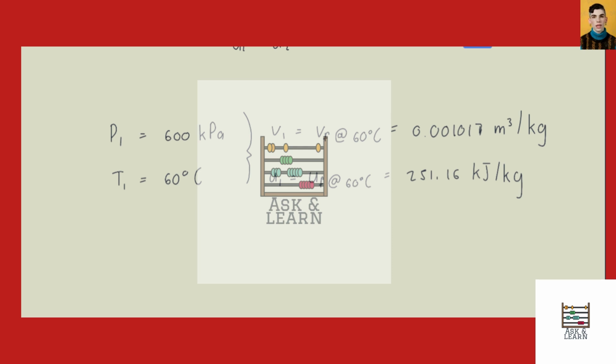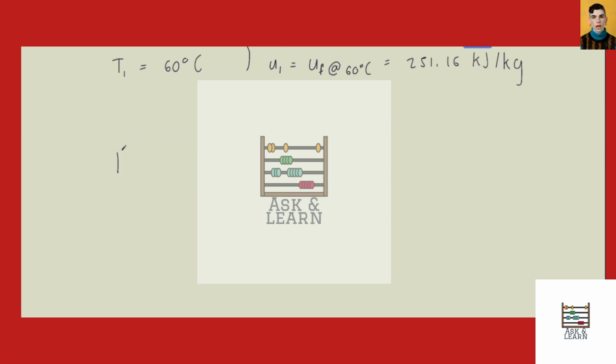We now assume the final state in the tank is a saturated liquid-vapor mixture, and we can determine the quality. So the assumption will be verified if you get a quality between 0 and 1. The pressure, P2, is 10 kilopascals, and u2, remember, is equal to u1. So if we use the tables, we find that vf is equal to 0.001010.